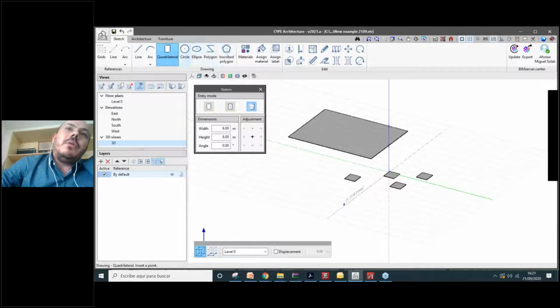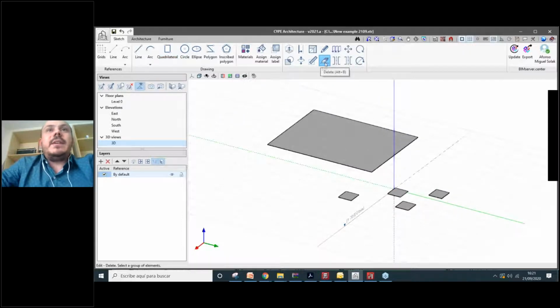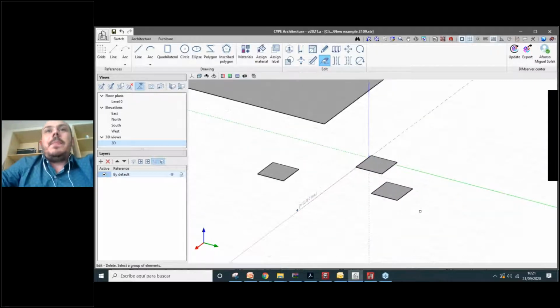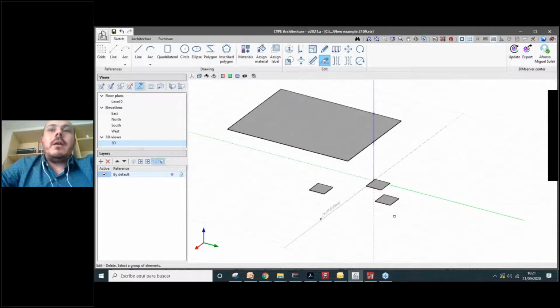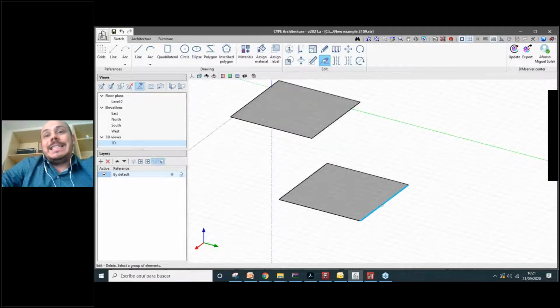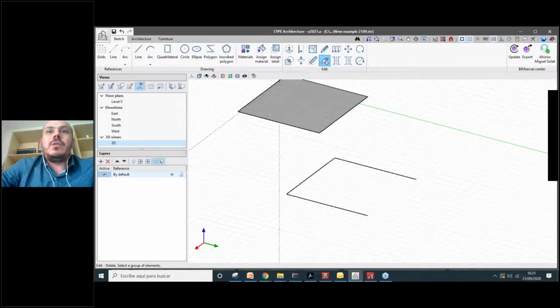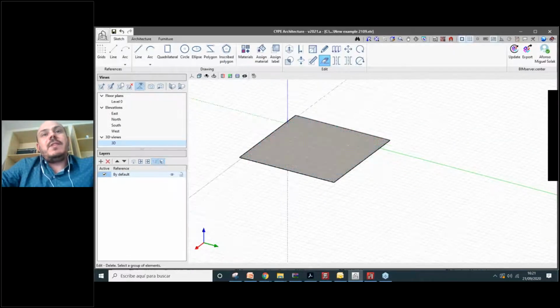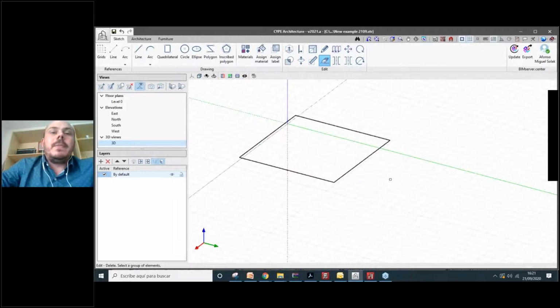Okay, I will mix. We use some of these drawing tools, then combine them with some additional tools to edit this geometry. So for example, here the first tool is to delete something. So we can delete just by selecting the information that was drawn before. When we have a surface, the surfaces are associated with some lines. So when we delete one of these lines, the surface is broken. So the surface is gone in this case, but not all the lines. Okay, and we can delete just, for example, the surface and maintain the lines. So it's quite easy to do that.